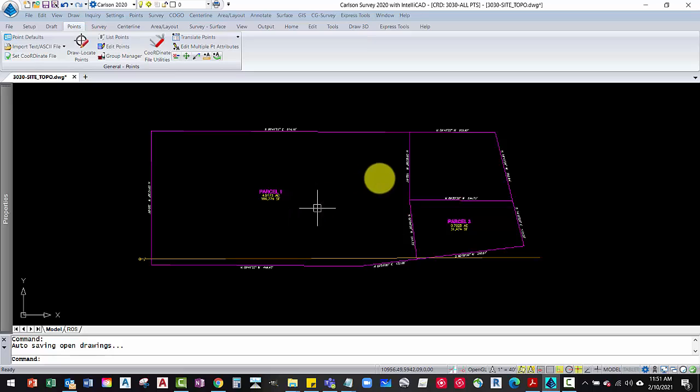If you use that as your base map, that leaves our settings the same and can work out a lot better for you. The first thing we need to do now is start bringing in points that we got from the field. There was a field survey done so we can know where to put this. We know it goes up here somewhere in the upper left-hand corner, the northwest corner, which is this existing home with the driveway and garage like I just showed you. But we don't have anything to represent that right here, so we have to pull points in so we can draw off the points.